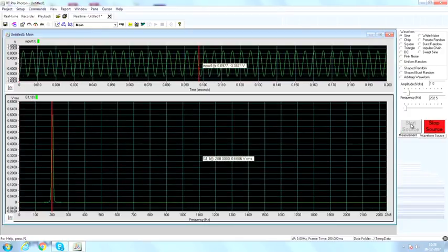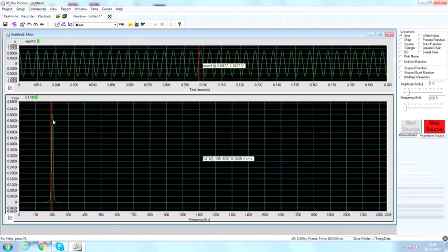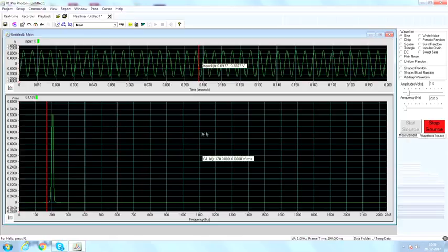You see, if I move the cursor here, I am quite not getting it, because at 200 it is giving me a value of 0.606, at 205 it is giving me 0.606, and at 210 it is coming out lower. So I know the value is somewhere between; if you look closely here, it is almost a horizontal plateau. Okay, because my delta f is only 5 hertz. If delta f was 2.5 hertz, I should be able to catch it.